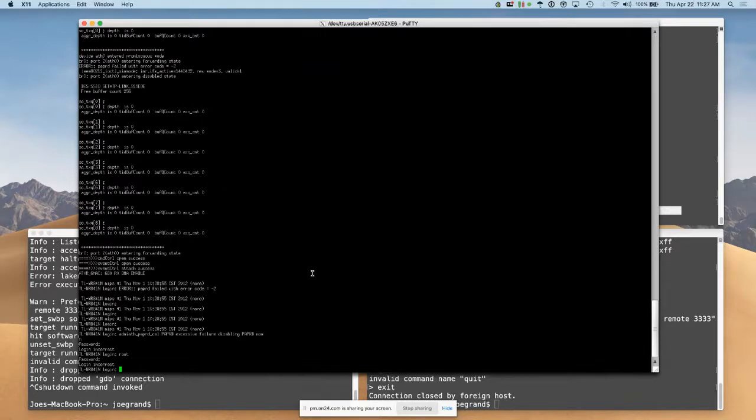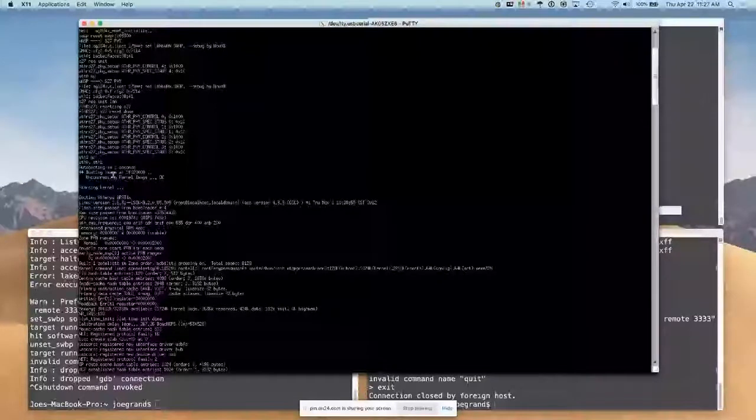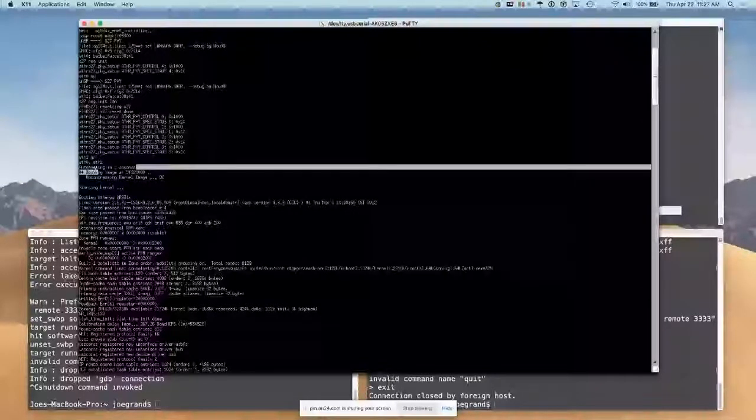But I don't know if you noticed, early on we see here it says auto booting in 1 second. So there's actually a bootloader on this system that we can pop into and abort the boot process, and then get dropped into a bootloader and do some really interesting stuff. So let's see if we can do that. Let's power cycle the system.